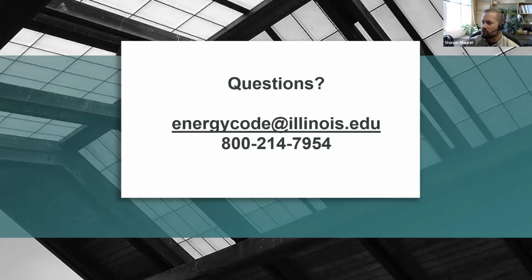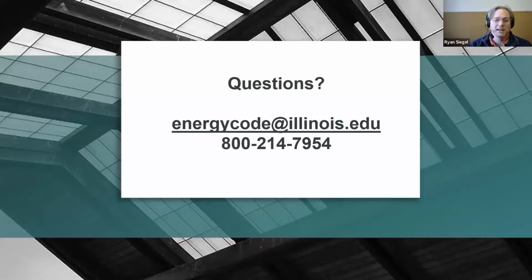We'll go ahead and share our poll results before we jump into the last few questions here, since we've got those in. It looks like most people picked up that, yes, the difference between commercial and dwelling units is all of the above. So the pressure is higher in commercial, air leakage volume allowances are a little higher, and commercial has a corrective action grace range, whereas residential does not. And for the 10 points, we are trying to drive towards a 2.5% improvement. So 0.25% per point times 10 gives you 2.5% improvement for that.